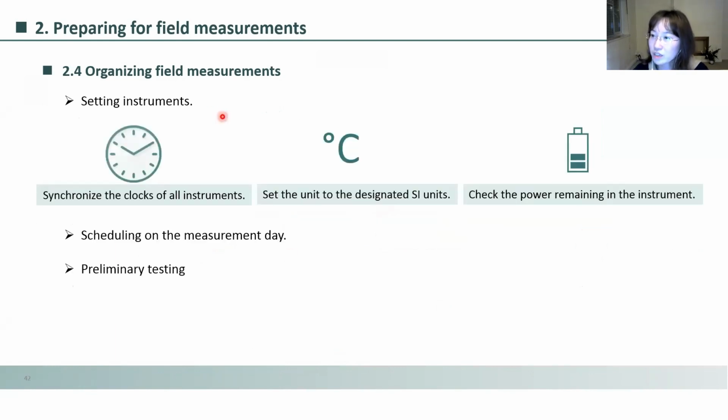And before you conduct the field measurement, don't forget to synchronize the clocks of your instrument, set the unit, and check the power remaining in the instrument. And a preliminary test is also an important point because it can be regarded as a rehearsal for the live measurement.